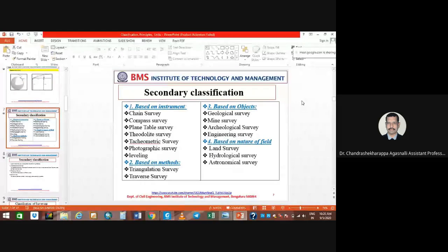So for that we go for high resolution data. That's all photography: take the satellite imageries, or the aerial photographs, or you can use a drone survey, take the images and plan with them. That's the best one. Okay, right.